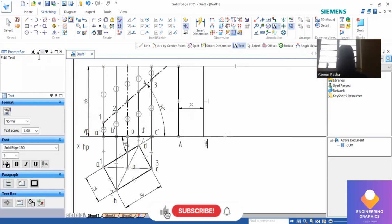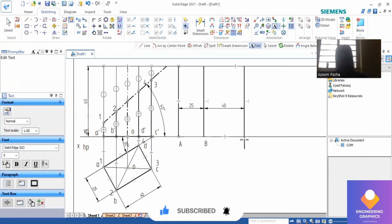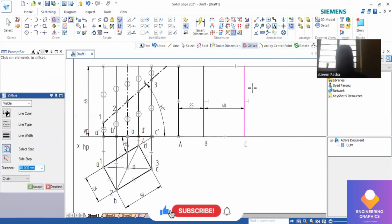From BC it is 40 mm. Again I'll use the offset command. And again from C to D it is 25 mm. Using the offset command I will give 25, enter.